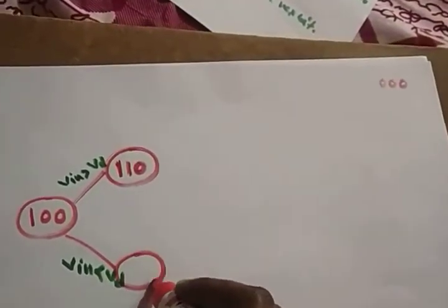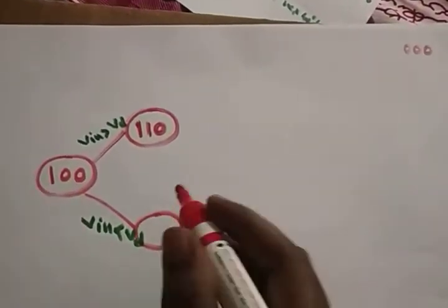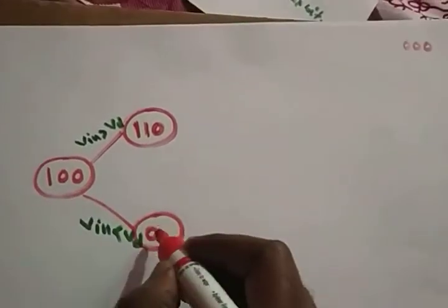And the other one, if Vin is less than VD, what is the function? It will reset the previous bit and set the present bit, the next bit, right? The previous bit is 1, so you have to reset that 1. Then you have to set the next bit. Hope it's clear. I just want to explain one more time.